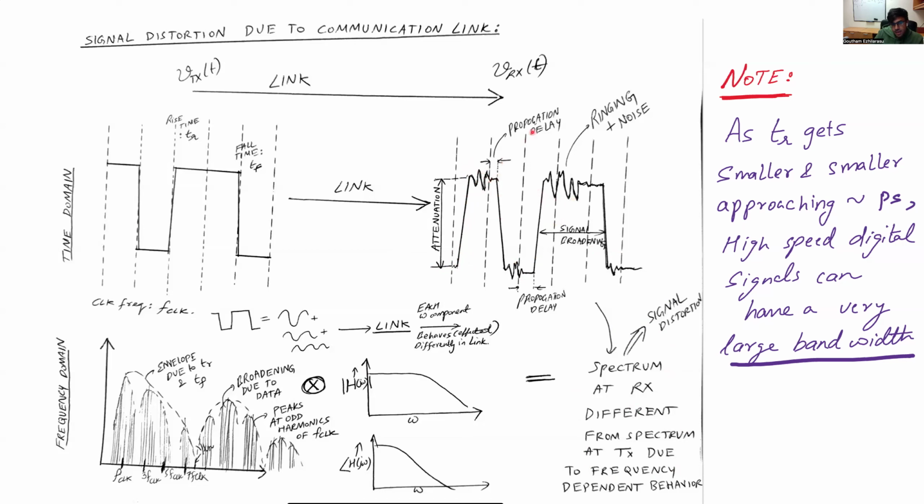So for example, you see this original signal, and these instances where the signals are sampled, which is in reference to a clock, would be the same at the transmitter and receiver because the clock is synchronized at both. So you see how originally the signal transitions at this time instant. But now at the same time instant, the signal has been shifted slightly forwards, which means the signal is slightly delayed. And this delay is because of the time it takes for the signal to go from the transmitter to the receiver.